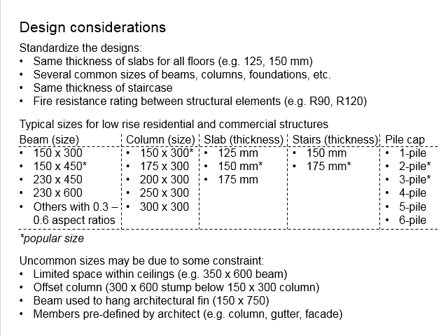Next, if you see a star here, this represents the most common size that you can see for different types of structural elements. If you are talking about low-rise residential structures, most of the members will fall between 3 to 6 meters, and most likely it's going to end up being a 150 times 450 section. Next, we look into the columns.